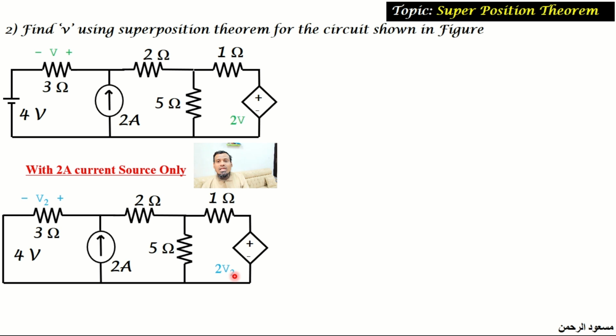So we will use the node analysis method to find what the voltage V2 is, so that we need to use a lesser number of equations rather than using mesh analysis with more equations. So for that, let us consider the nodes. Let us assume this is node A, this is node B, and this is node C, which is the reference node. As you all know, in the nodal analysis method, the voltage of the reference node will be taken to be 0. So now at node A, let us assume the currents as given to you here.